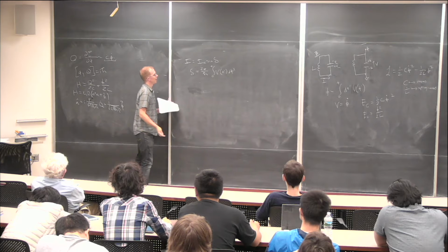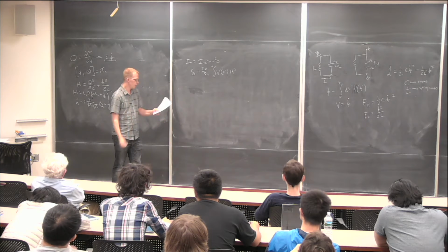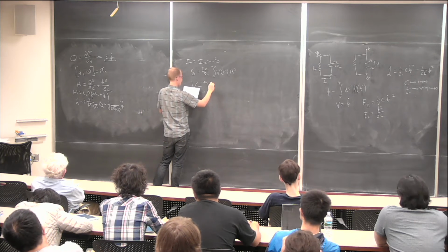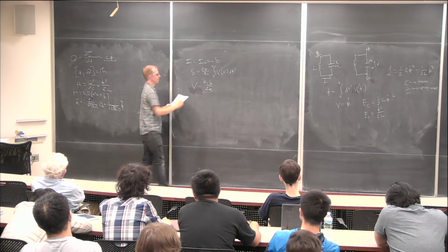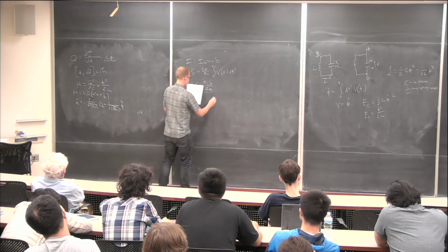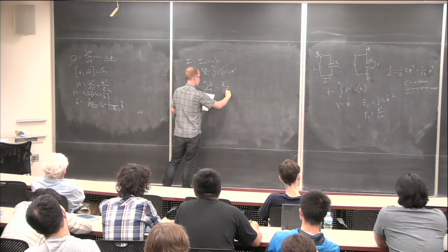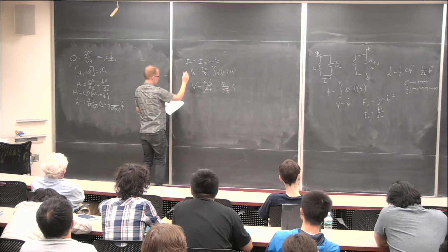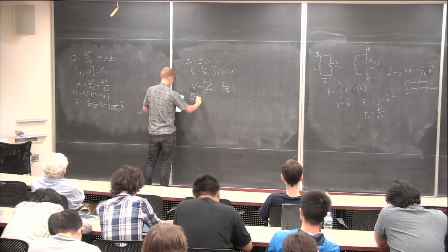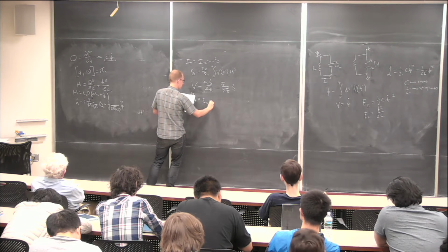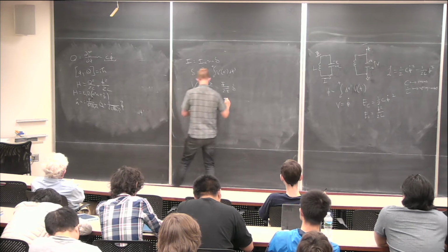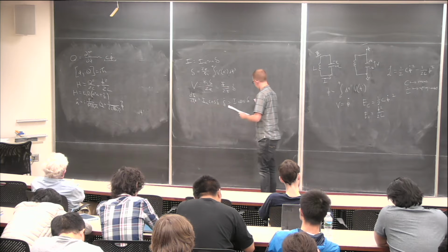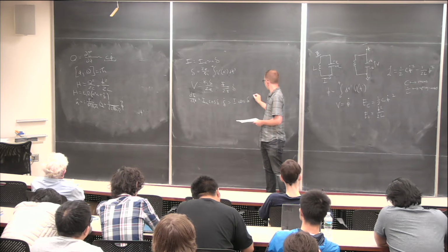If you want to see why this is exciting, you can do a little bit of math. The voltage is h bar times delta dot over 2e, just taking the derivative of this. If you want to write that in terms of the flux quantum, that's phi naught over 2 pi times delta dot. That's just how the flux quantum is defined. And if you take the derivative of the current equation, dI/dt is equal to I_C, the critical current, times cosine delta times delta dot, which is equal to I_C cosine delta times, from up here, 2eV over h bar.